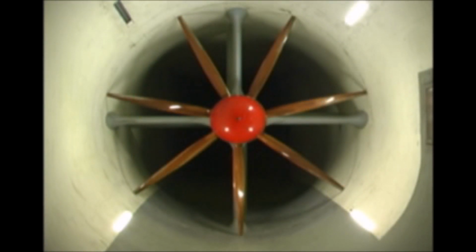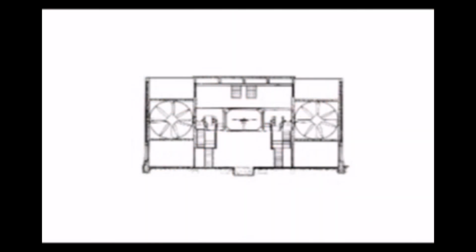These motors power two custom-designed 7-bladed fans. The designers of these fan blades chose Honduras mahogany for its excellent fatigue and fracture characteristics. Each fan is 14 feet 9 inches in diameter with a quarter-inch gap between the blade tip and the wall.